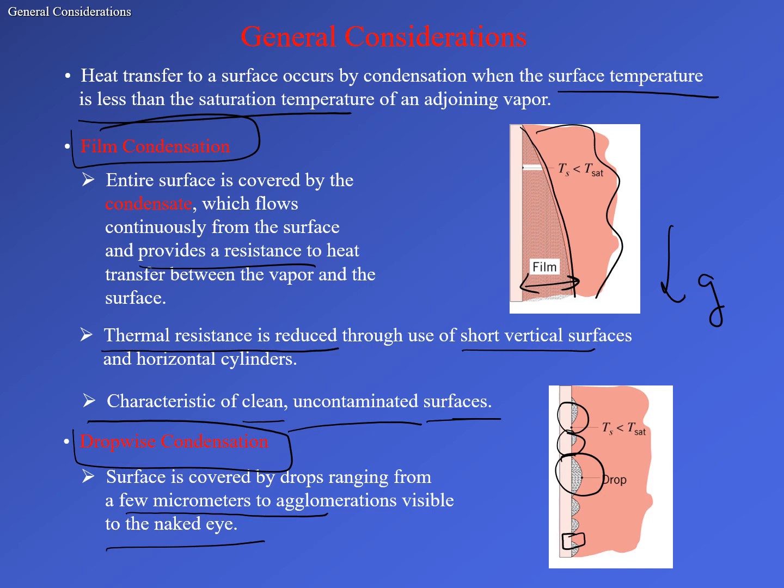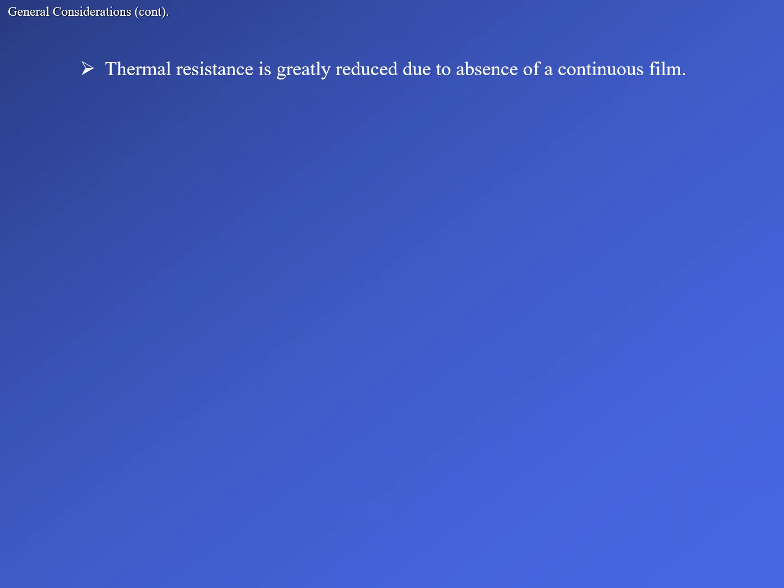And when these drops become larger than a particular size, because of the ratio of the gravity force to the surface tension force, which is typically called the Bond number, when that Bond number becomes large, the increased size of the drop tends to make it fall down, and the surface cleans itself in the process.